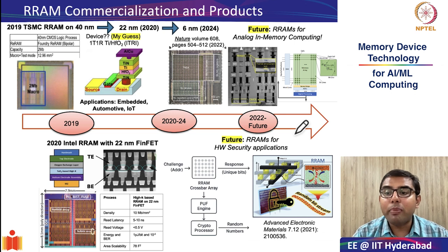So this analog memory behavior, which has more than 100 states in a single device, may not be very good for digital applications due to signal to noise ratio, but they are excellent for analog computing for low power AI hardware. Also, we saw the issue of sneak paths, which was preventing the scaling of RRAMs into crossbar arrays, and how these were mitigated with array biasing and selector device configurations.